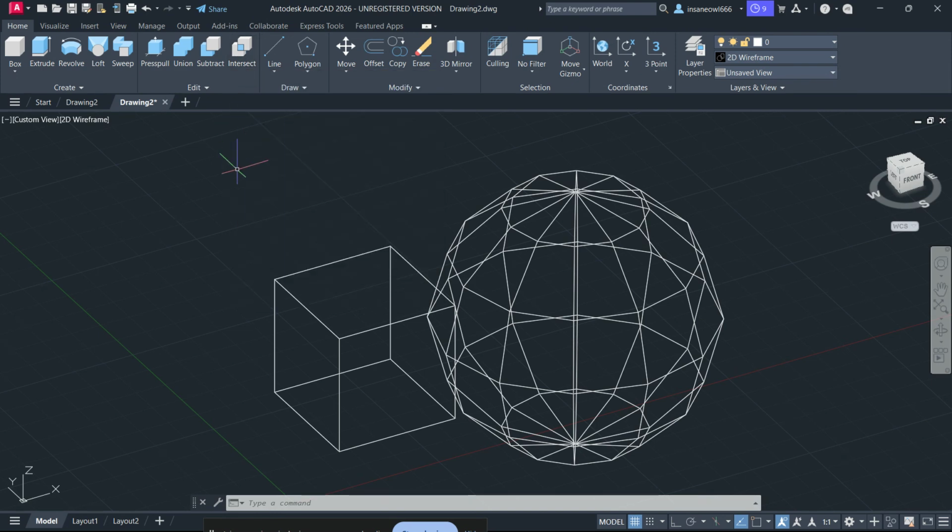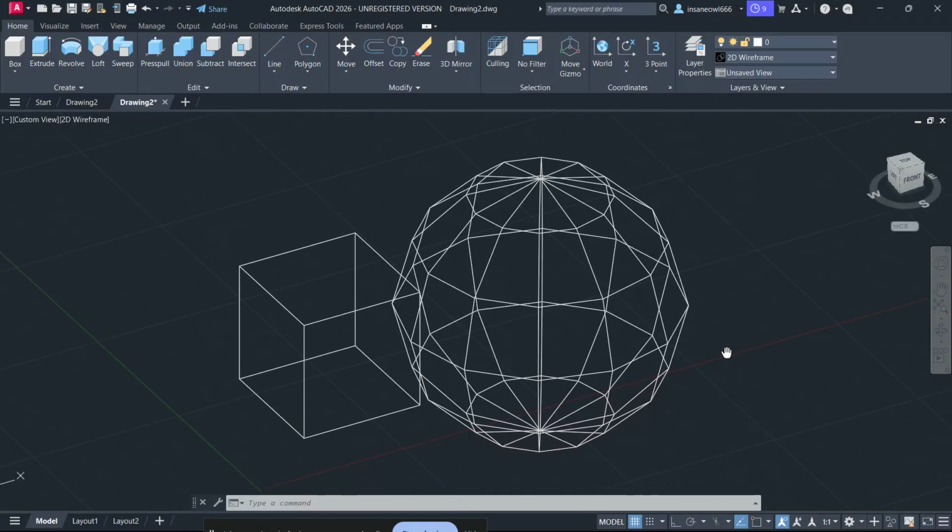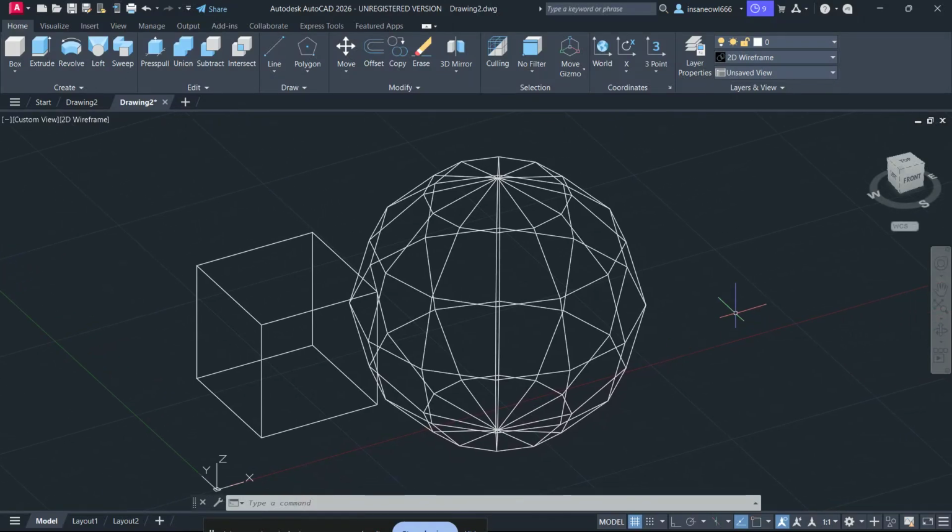Let's get into it. First, it helps to understand why this happens. Error 18050 often appears when two objects are only grazing each other instead of clearly overlapping. For example, they may touch at a single edge or a single point, and that can make the Boolean engine fail. Another common reason is non-manifold geometry, which means the result would create zero thickness areas that AutoCAD cannot properly define as a solid. A third issue is self-intersecting loops, where a solid has internal faces or broken geometry that makes the body mathematically invalid.